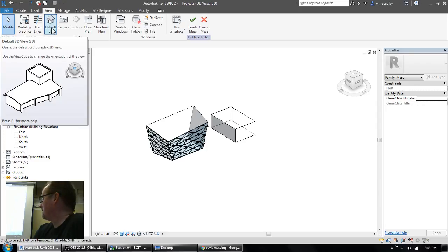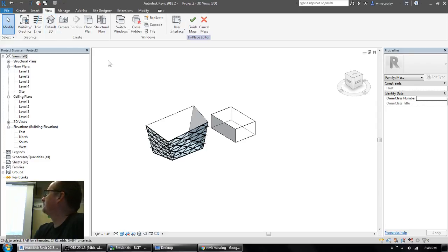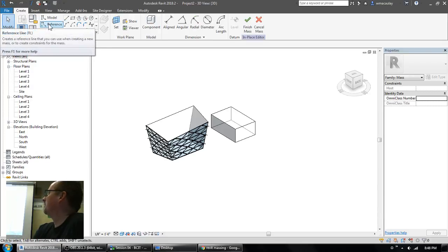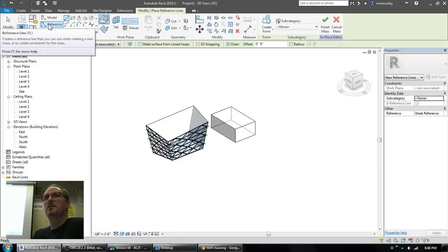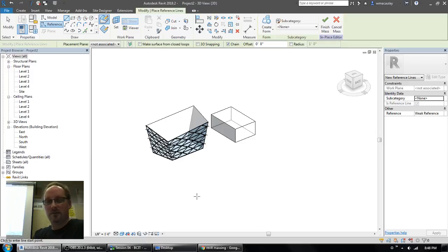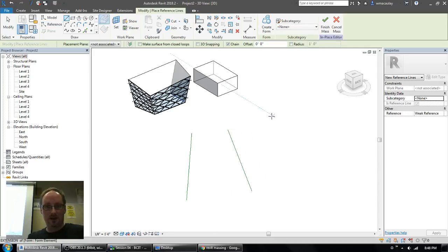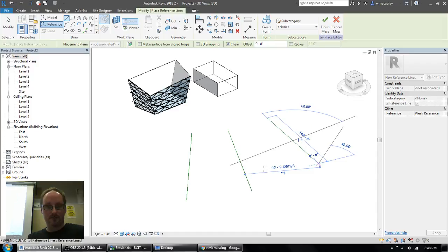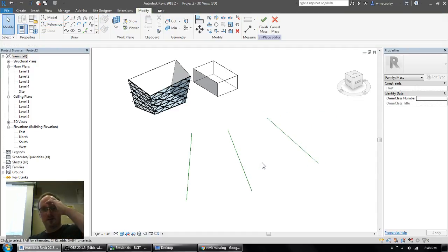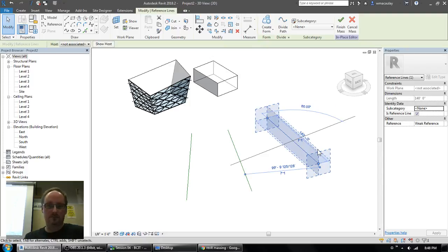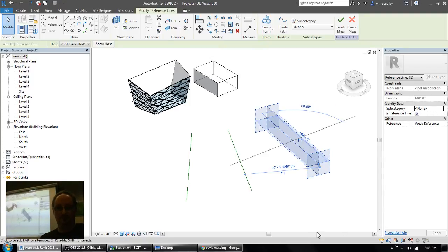And no matter what you draw in there, you can just preserve it. You don't need to get rid of anything at this point. And we're going to go to the Create tab, and we're going to use Reference Geometry. And we're just going to draw 3 reference lines, and then we'll talk about them. And make sure that they diverge. So you're going to draw 3 separate reference lines that diverge. And once you're done, hit Escape once, and we will explain these different reference planes.